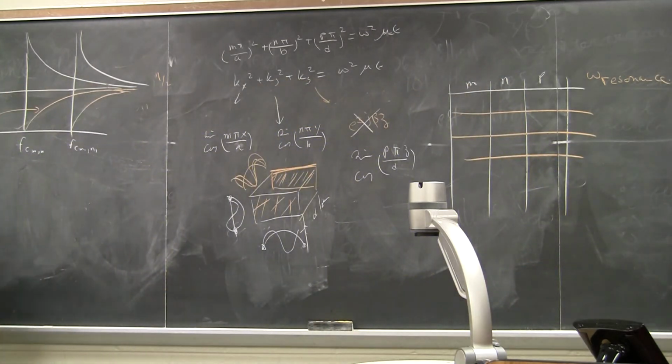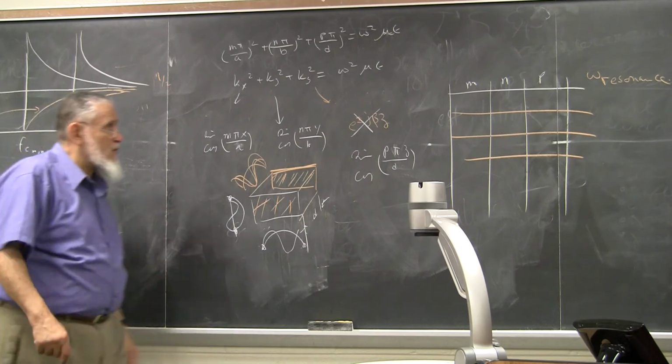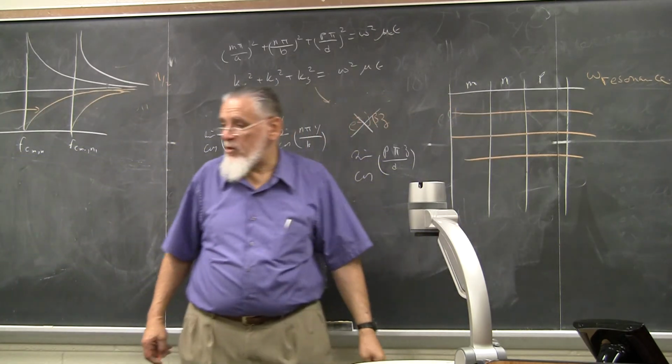Think about it in terms of the L and C, right? Omega squared LC is equal to 1. That's the resonance frequency, right? So if you put the L and C and put a different omega other than omega squared LC equal to 1, you won't have a resonance. The resonance will be happening only at the frequencies that will meet that particular condition.